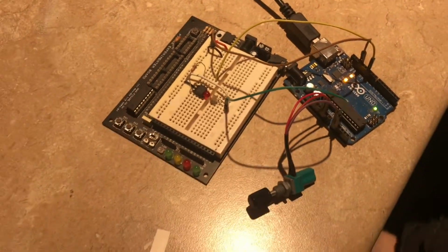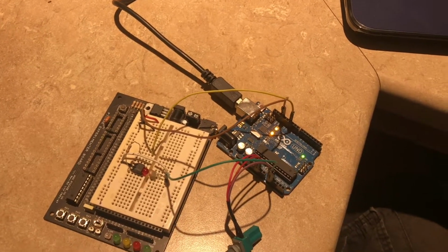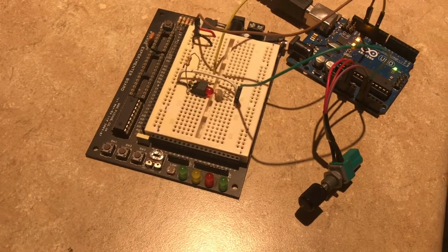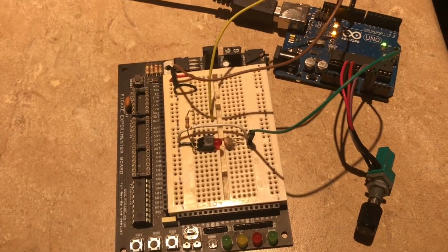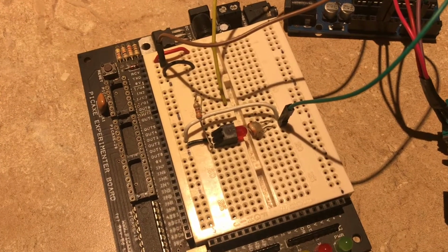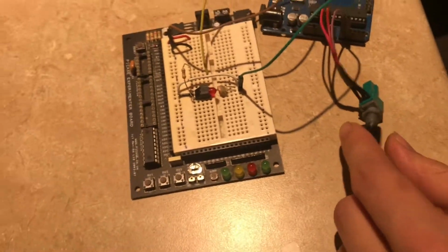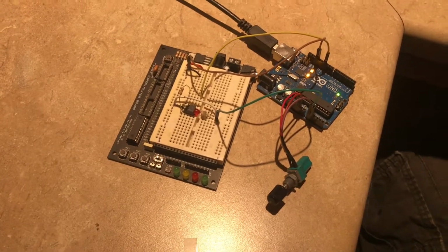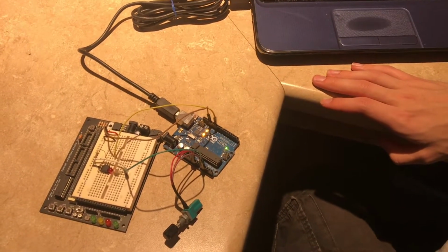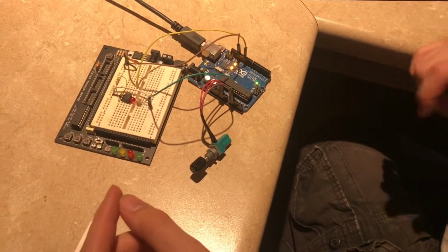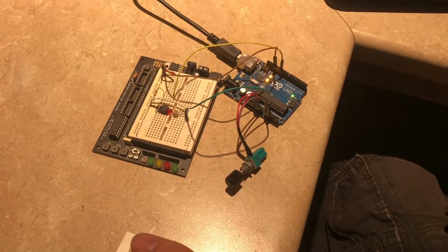So at the moment I am working on something called a PID controller, and its purpose is in automation, or just controlling devices. You're trying to get an output of some kind to match up with a set point, a control. So giving a real example, say you have a motor you want to spin at exactly a certain speed. You could have a dial that you adjust to set the speed, and then an encoder or a speed sensor of some kind that monitors the motor, and some kind of smart control electronics that adjusts the speed of the motor whenever the input changes. For example, if you were to grab the motor and force it to spin slower, then the control electronics should know that it has to increase the power to the motor to keep it going.